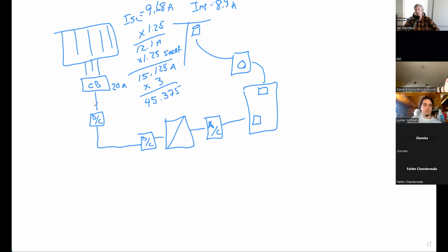So we need wire that can handle 45.375. So you would look up in your table, I forget which page it is, like 104 or something like that. Each edition. 104. What is 104? Yep. Hey, what do you know? That's really sad that I remembered that. So, all right, then you look up in there, and anybody looking at that table at the moment, what size wire do we need?